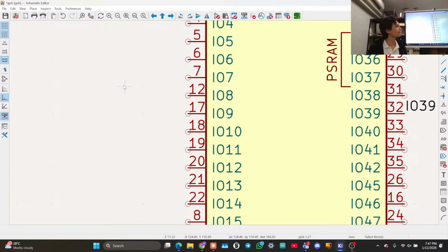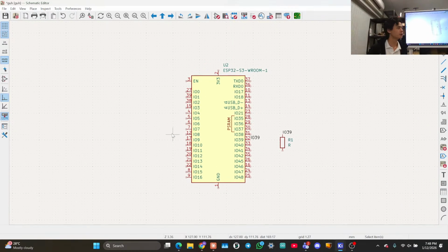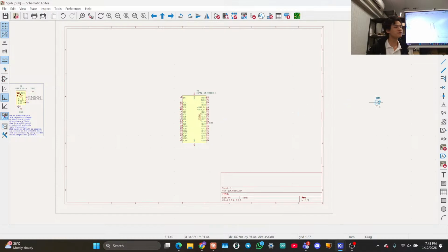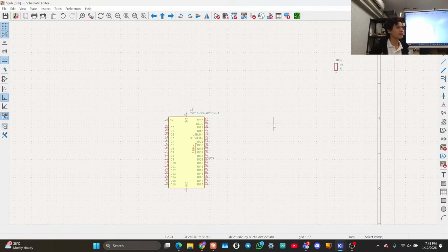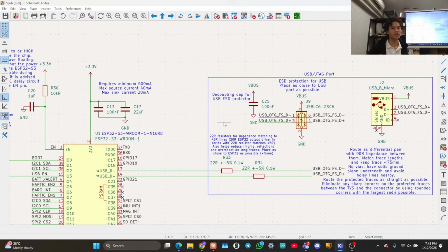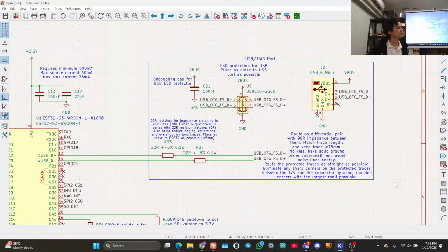Where did you put your nets, like other parts? You put them wherever you want, however it makes sense. If you just make this fly away somewhere here, and then you have a bunch of stuff in between, then someone reading your schematic is not going to assume that this is in any way related to this. So schematic readability is important. You try and put related things close together. And ideally you box them up like this. This is just a blue box which I graphically draw.